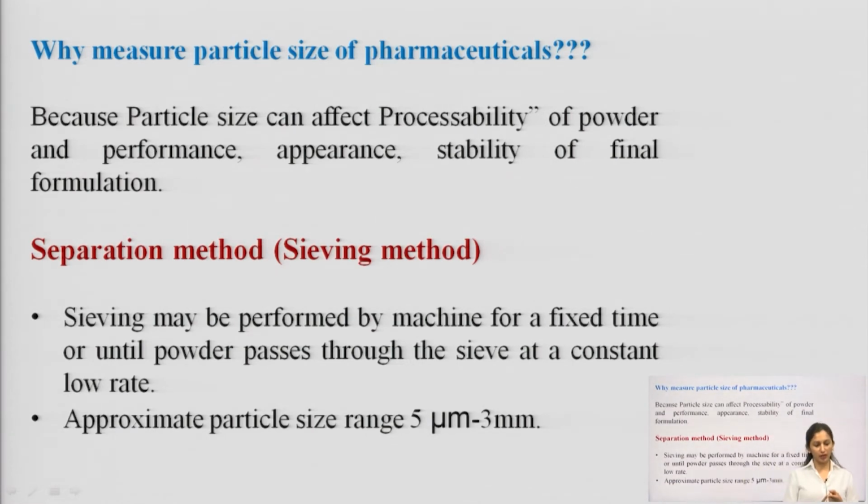So, among the fundamental properties you have to study two properties, and next we will study the rest of the properties, which are derived properties. First fundamental property is the particle size, and the second fundamental property we will study is the powder particle surface area. For the determination of powder particle size along with powder particle size distribution, and what is the difference between particle size and particle size distribution, we have already discussed in our previous lecture. So, for the determination of powder particle size there are two methods. One is the number distribution method and the second one is the weight distribution method.